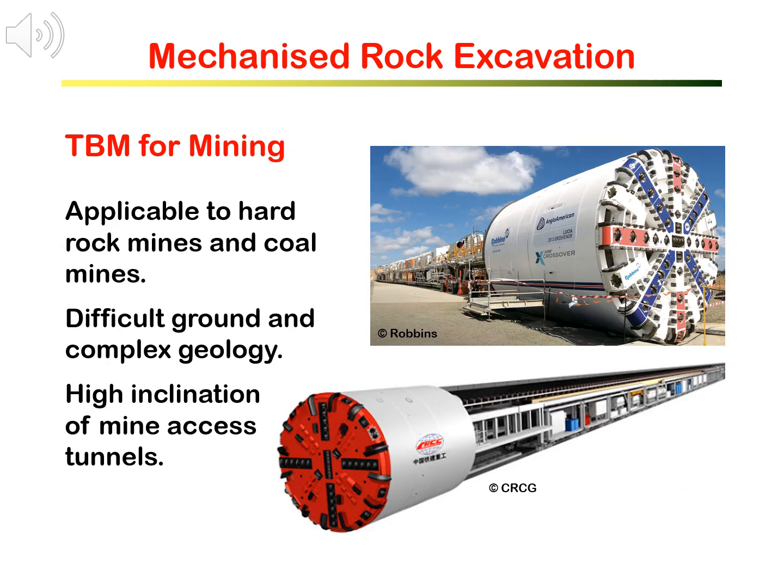TBMs can and have been used for mining, for both hard rock mines and coal mines. Many of the challenges faced by TBM tunneling in difficult grounds and complex geology are also faced by TBMs in mining, in terms of extremely hard and abrasive rocks, mixed ground, high stress, and squeezing. There are additional challenges in mining applications, for example, high inclinations of mine access tunnels.